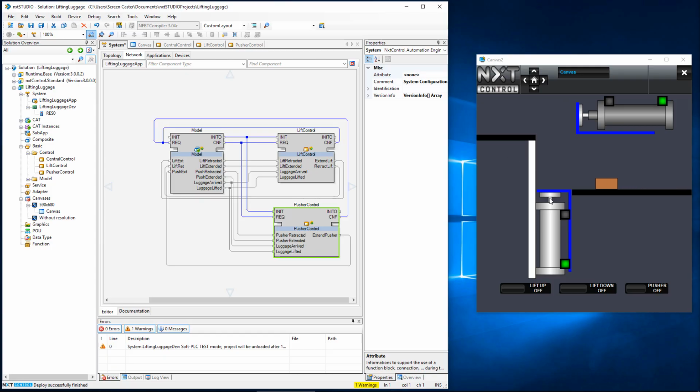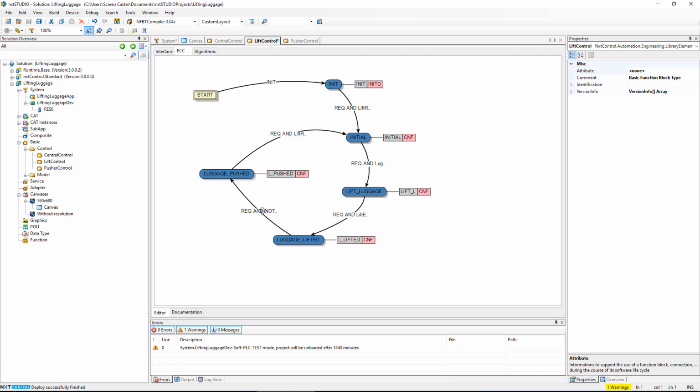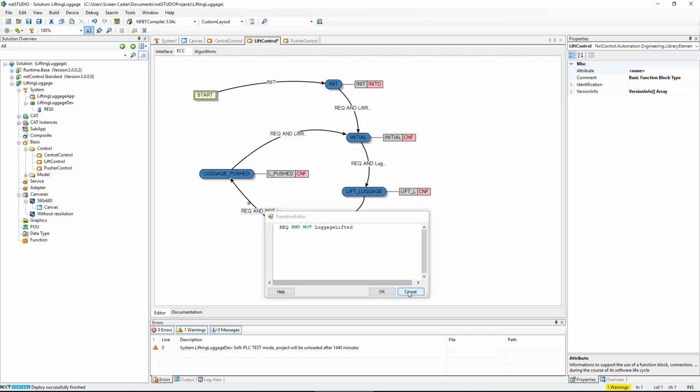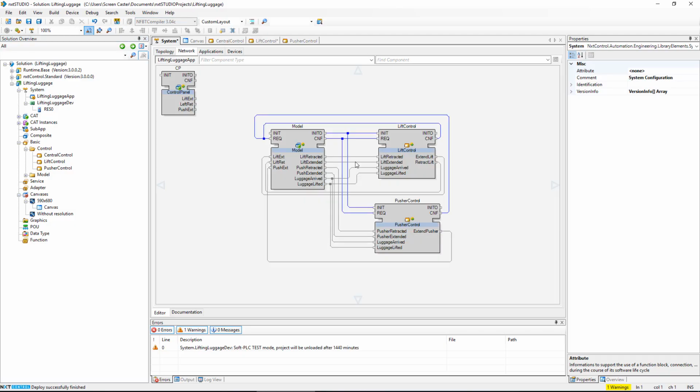This lift starts to retract even before the workpiece is fully pushed. That means that it's trying to push, but then, yeah, well, that's not correct. And that is where I had a bit of concern when I was writing this. So maybe we should do a different approach, and let's use events to do that. That is, what we will do is we will tell the lift controller that the pusher controller is done pushing via events. We are using 61499.